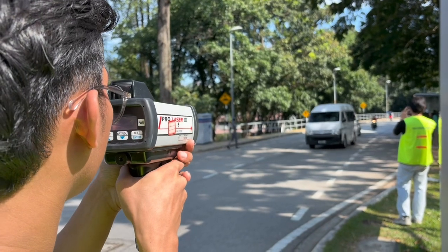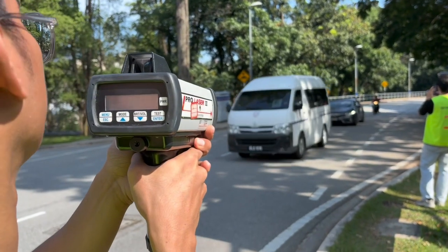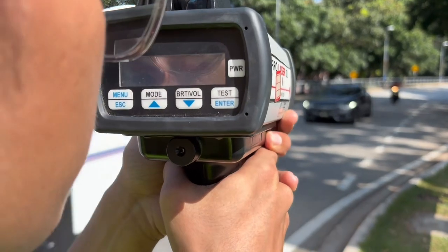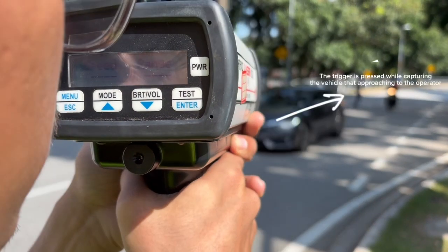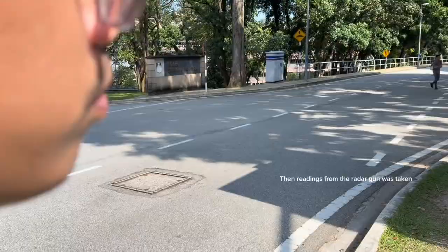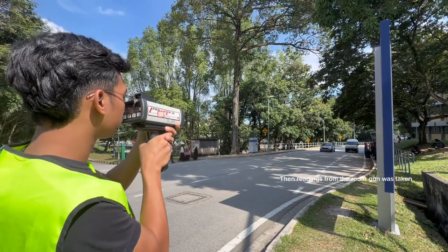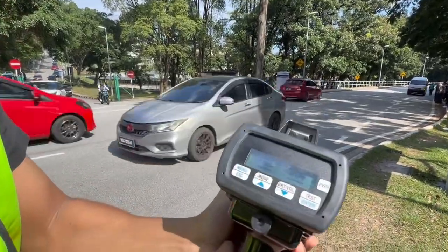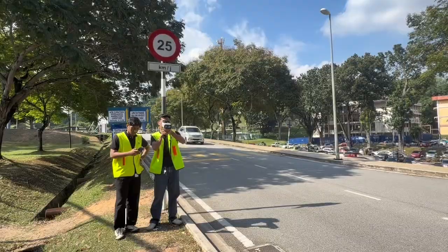Procedure for spot speed study. Firstly, the radar gun is switched on. Next, the trigger is pressed while capturing the vehicle that is approaching the operator. Then, the readings from the radar gun are taken and recorded. Then, the data collection continues until we reach 50 data points.